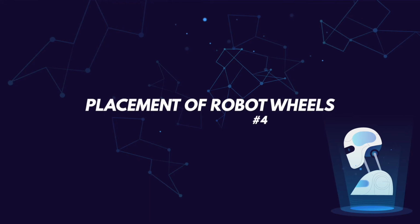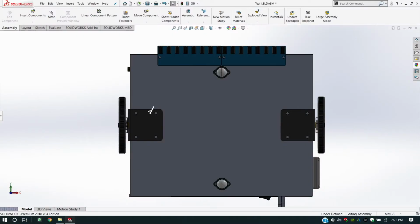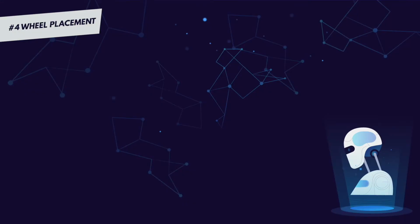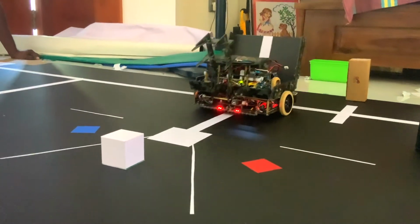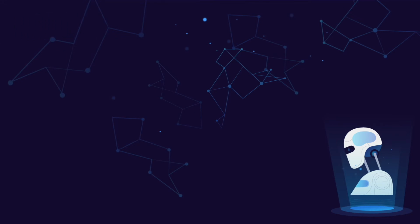Placement of robot wheels. We decided to bring the wheels of the primary robot to the center because it has to carry another robot on its top. So, we should consider the center of gravity when it travels with the secondary robot. We realized that it is better to have the wheels at the center because it lets us make all the turns perfectly without changing its axis and position. This makes it very easy to control the robot.